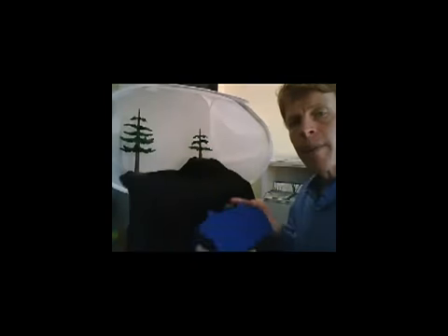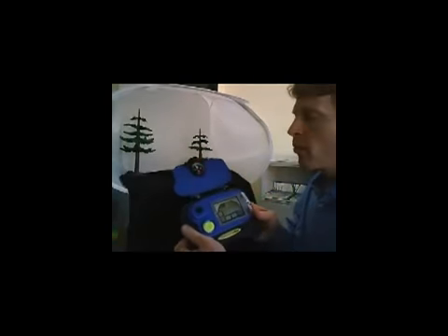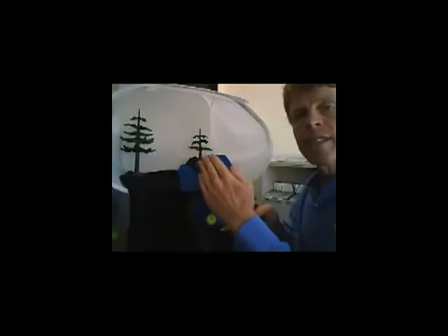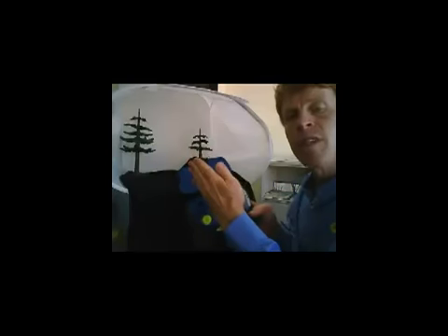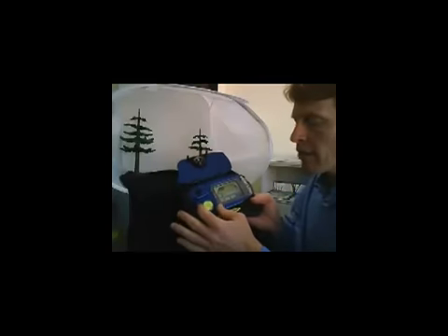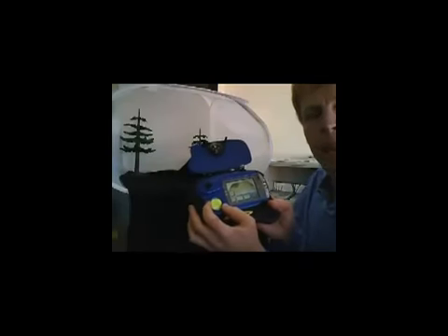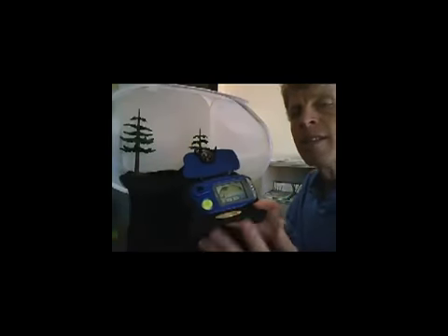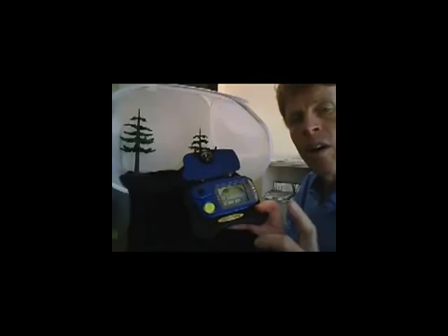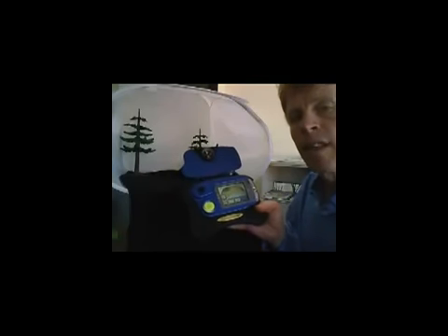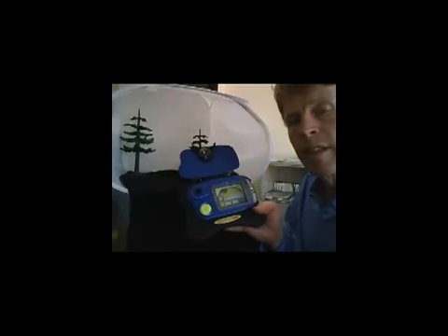Now, whenever we make a measurement using the SunEye, we need to orient the SunEye so that it's facing magnetic south using the compass as a guide, and so that it's level using the bubble level as a guide. This is a key point using the SunEye. Always magnetic south, always level, and that's regardless of your roof's tilt and your roof's azimuth.